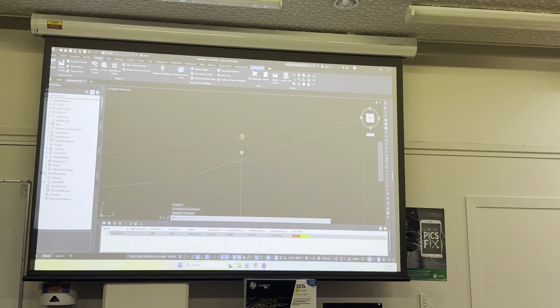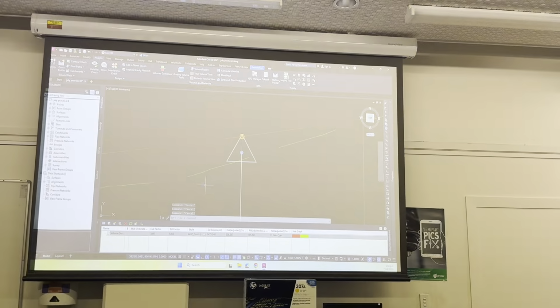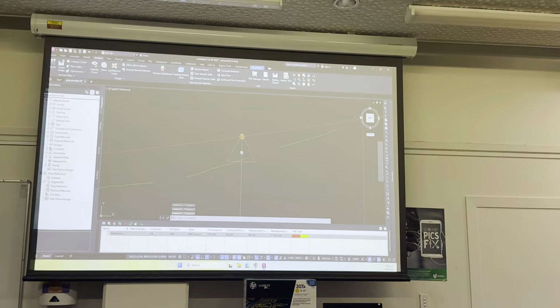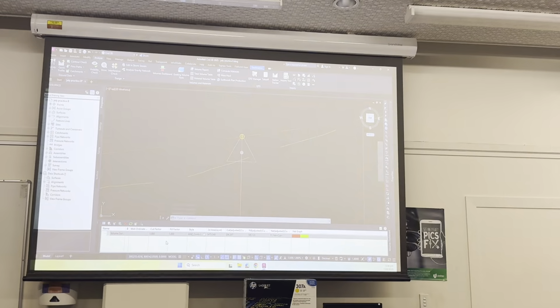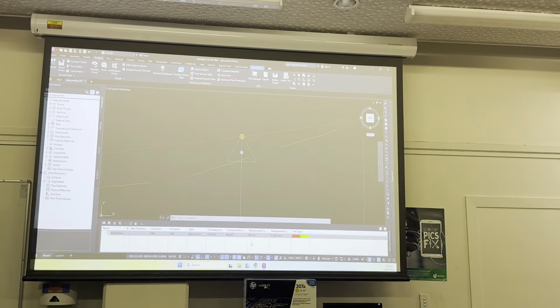You can try to get it as close as you can, would be better. Just leave it as 1-to-1 cut and fill. You guys know that's 1-to-3 though, if you use cut and fill. But for the purpose of this, just use 1-to-1. And just get as close as you can, where on the net graph you can see where it's balanced.